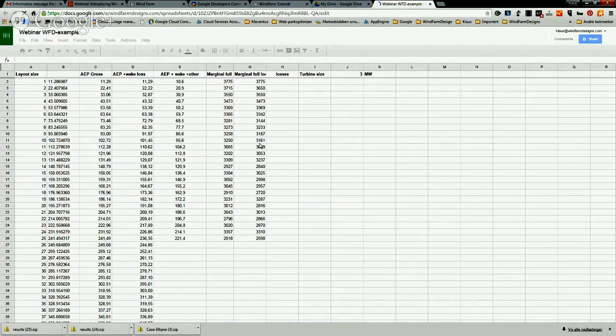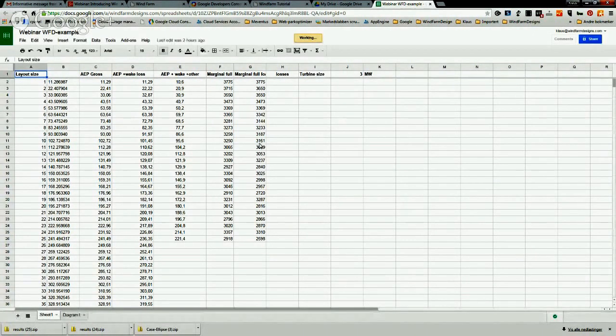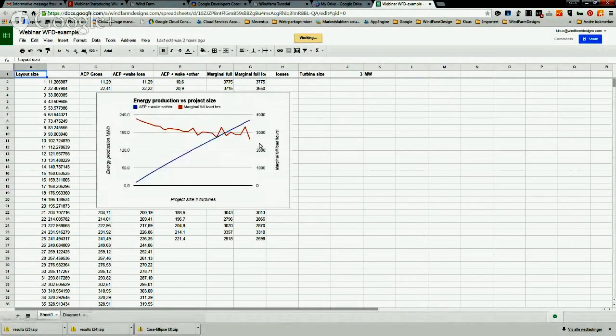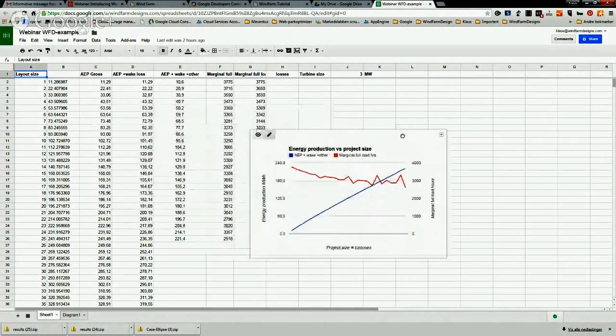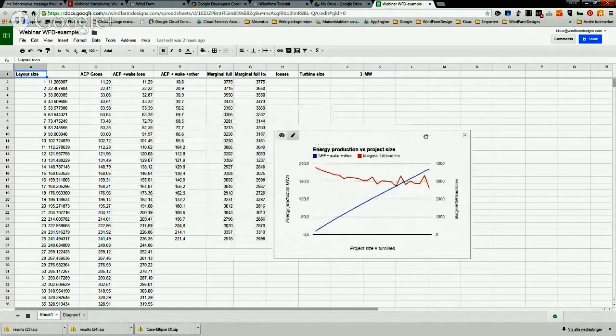In WindPro, it's a heuristic algorithm. That's the first difference. That is an algorithm where you're not necessarily guaranteed an optimal solution, but it gives quite good results, and it's based on trial and error. It tries to place turbines in a more or less systematic way. With our algorithm, which is based on formal optimization techniques, it does guarantee an optimal solution, but it only considers the elliptical distance, and wake losses are not included at the moment.